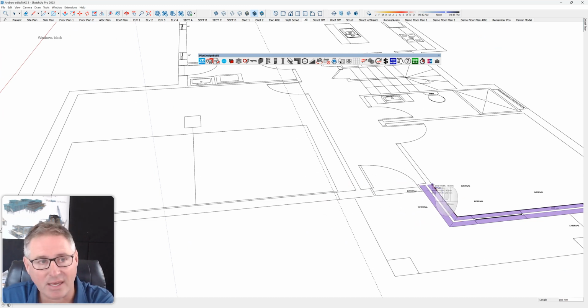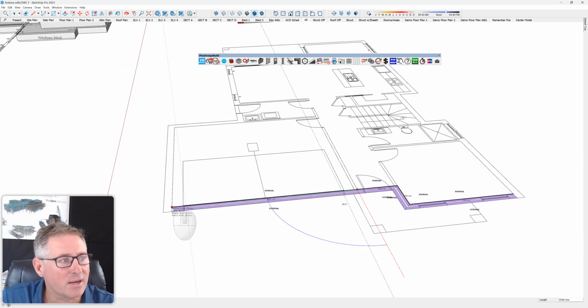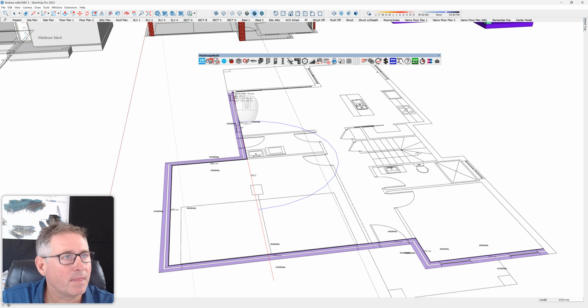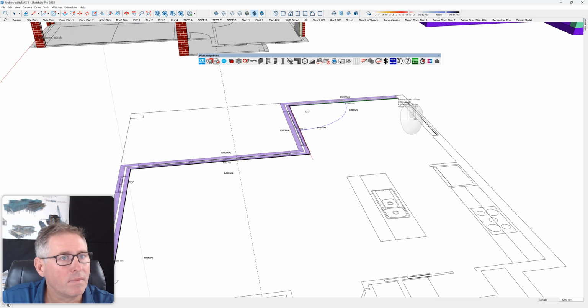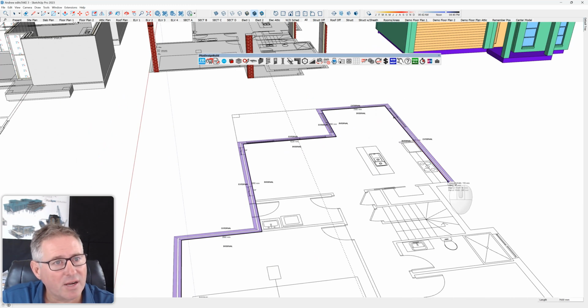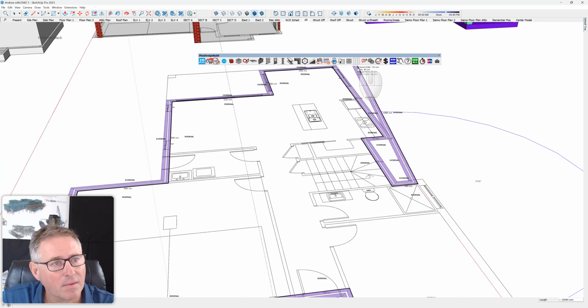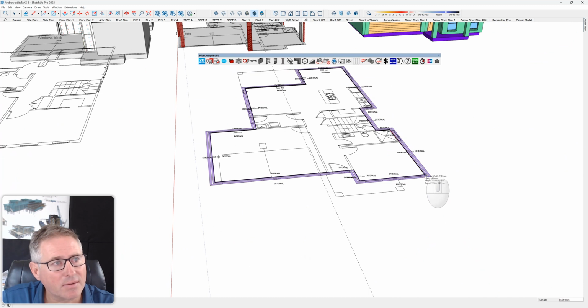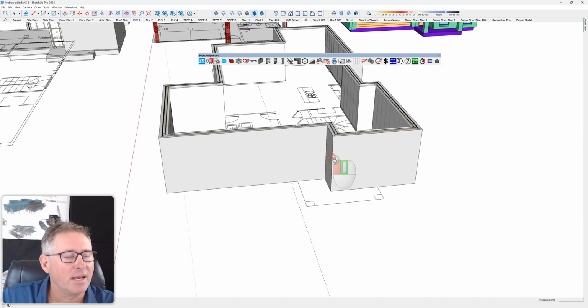Actually, I'm going to delete there, guys. So I should have gone to the inside of the wall here. I can stop here, and then I can go through to here. Shift again. Simple trace, guys. And you can see that joined together. If I was there and it didn't, I wouldn't have created a loop. I want to create a loop in this instance. Right, now I have my wall there.